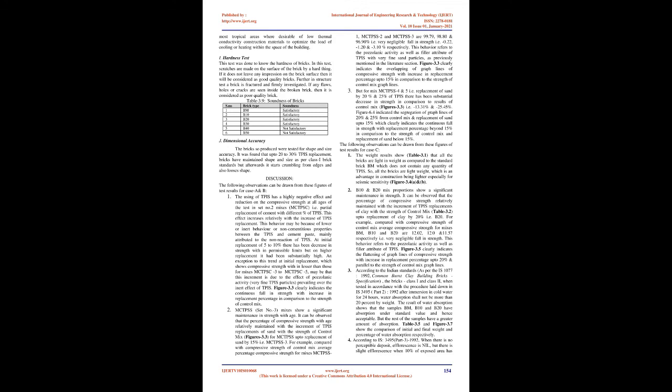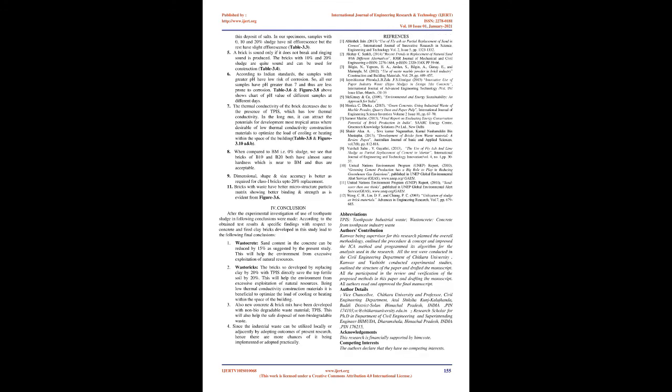4. According to IS 3495, Part 3, 1992, when there is no perceptible deposit, efflorescence is nil, but there is slight efflorescence when 10% of exposed area has thin deposit of salts. In our specimens, samples with 0, 10, and 20% sludge have nil efflorescence, but the rest have slight efflorescence, table 3.3. 5. A brick is sound only if it does not break and a ringing sound is produced. The bricks with 10% and 20% sludge are quite sound and can be used for construction, table 3.4.